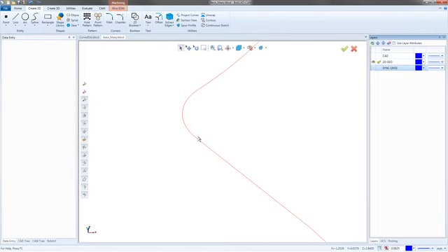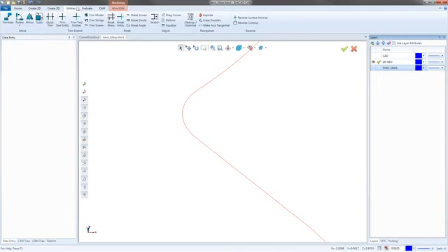The other option, the other problem you could have with it would be any duplicates. I've done it thousands of times where I go to extract edges and I end up extracting edges twice. It's just something that I've done a bunch of times. So if you accidentally do that, you go up to Utilities, Evaluate for Dimensioning. You go to Clean Up and Optimize. Now, Clean Up and Optimize reduces the number of entities within the drawing by joining curved segments and, this is the big part, getting rid of any duplicate geometry.